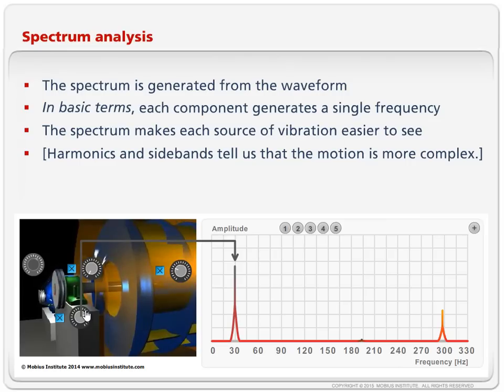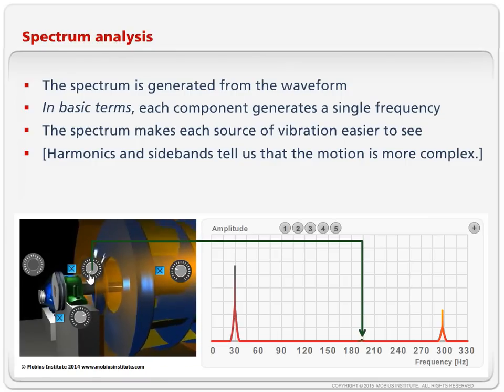Do I think this is going to cause the machine to fail, the structure to fail? Is it creating noise that's creating a quality problem or a noise issue for workers and whatever? But the question I should also be asking myself is, is this going to do damage to the bearings? Because while we're monitoring the condition of this machine and we've got this unbalance, we damage the bearings. That's one of the root causes of bearing failure, misalignments and unbalance and these sorts of faults. So now we've seen the bearings start to fail. The patterns are a little bit different to this, but you get the principle.